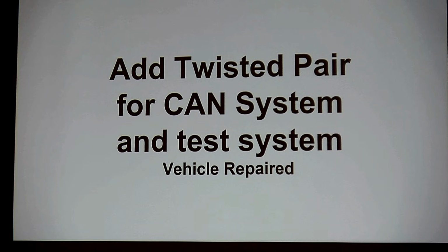You're going to do the same thing where I don't cut them. I'm going to just strip them back. I'm going to solder them, and then I'm going to put a good sealant on it, right? Liquid tape. I'm done.